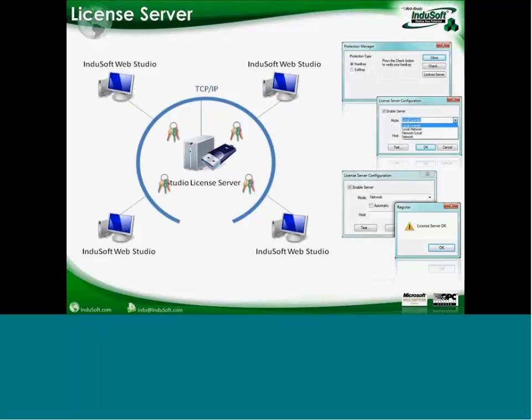With version 7.1 Spec 2 of InduSoft Web Studio, we also provide the option to use what we call license server, which means that you can have one computer in the network with a hard key, and in this hard key, you have the license settings, like the number of tags, number of thin clients, but also an additional parameter called number of concurrent servers.